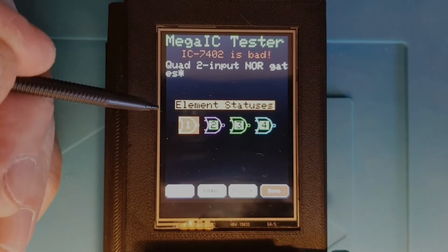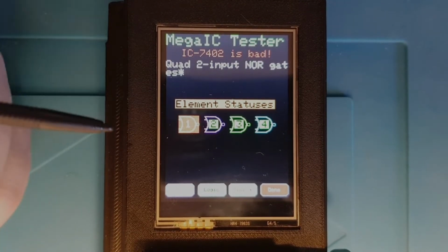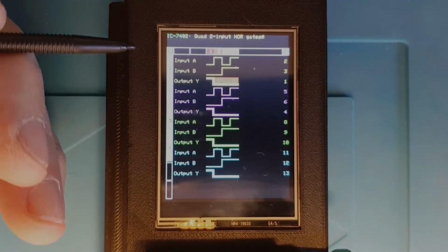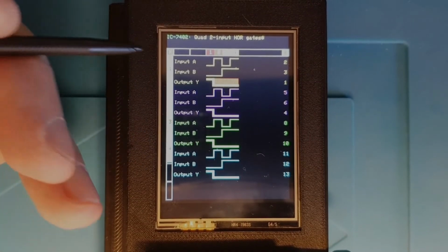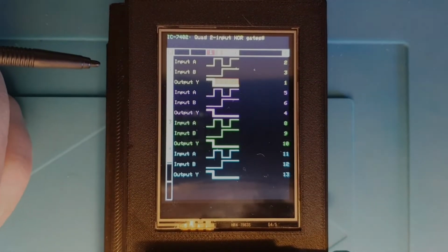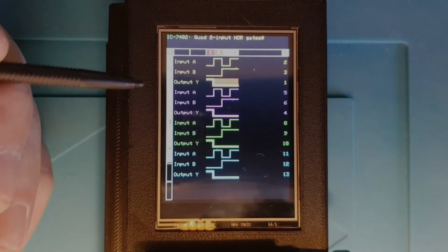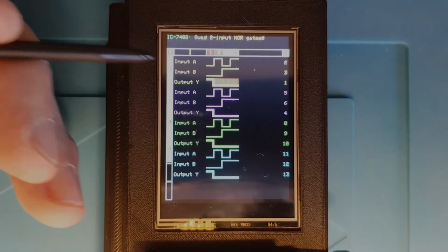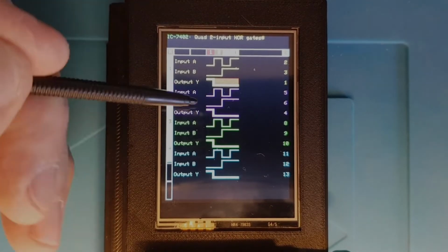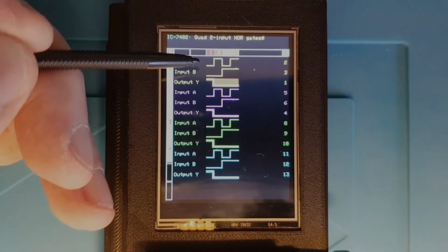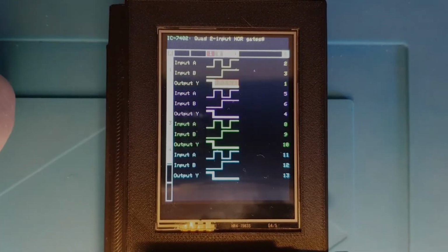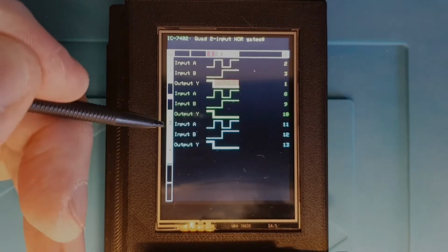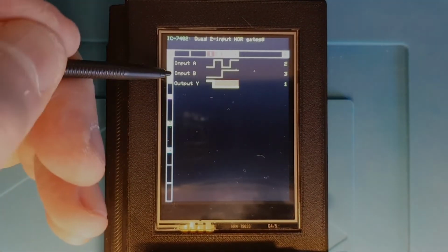So it's amber status because one of the elements has failed, and that's element number 1. Look at the timing diagram. Right, so this is a multi-element chip, so instead of showing controls, inputs and outputs down the side here, we've got one blob coloured in to line up with the 4 elements that we've got, and element 1 has failed. We can actually see here that it was okay on the first step, but then it failed for the next 3 steps, which is what that red thing there indicates. And again, we can just turn the elements off if we want to, or turn them back on again.